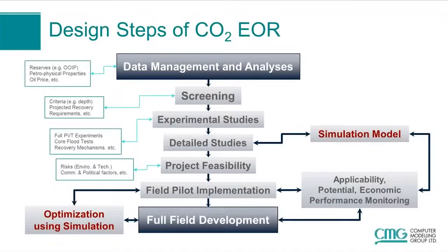Step number 4 is detailed studies. The reservoir simulation is a must for planning a full pilot and field project. In this stage, all the design parameters such as well pattern and type of injection are highlighted. Then the optimum recovery and required facilities such as pipelines are identified.